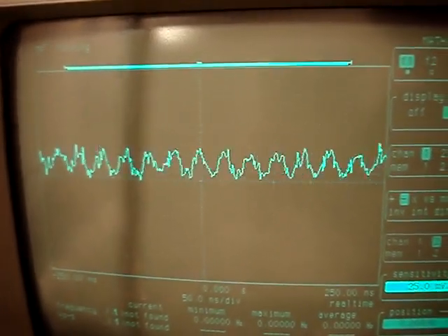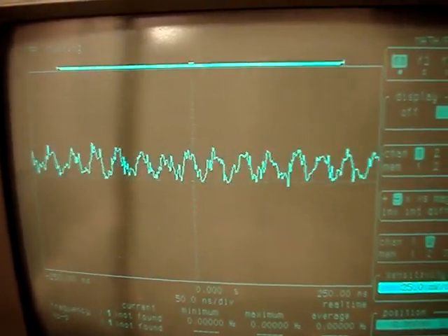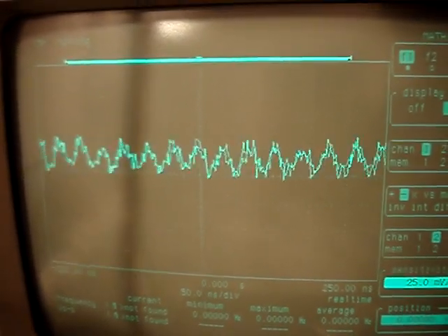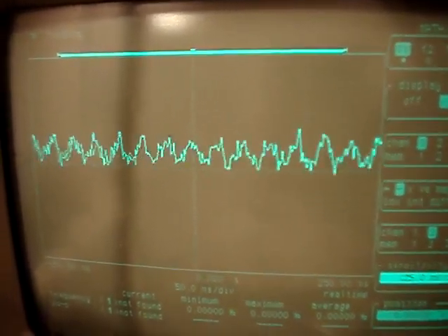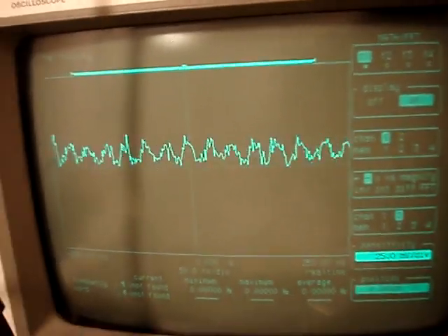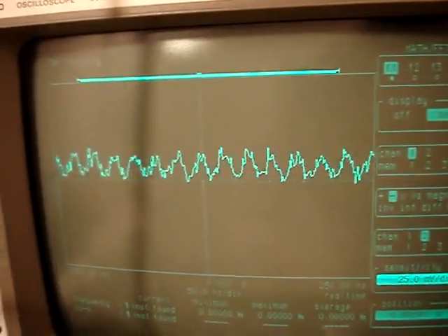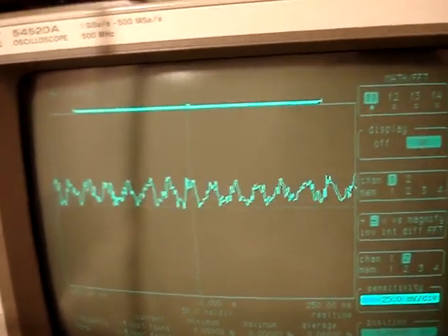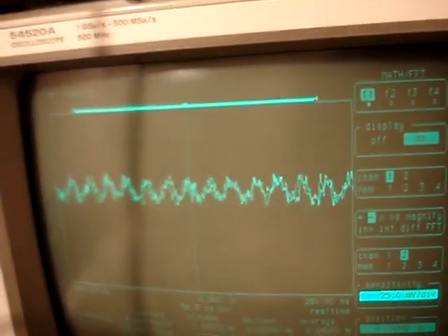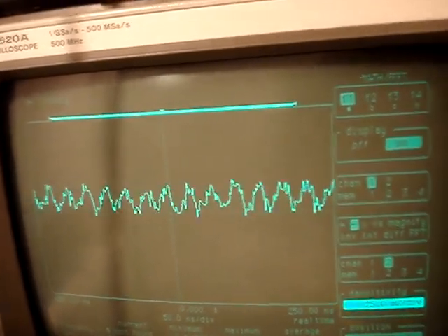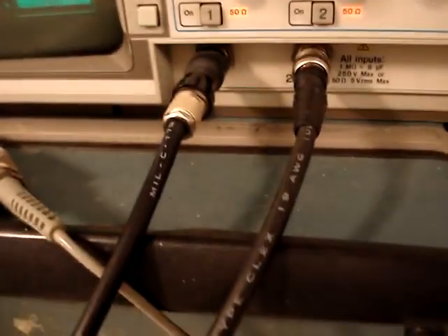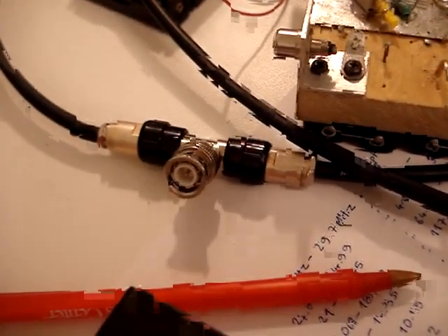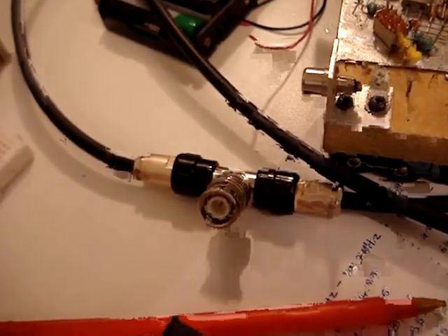this might not actually be the amplitude difference, but tiny variations in the phase difference between the two signals that may have been introduced either by the splitter or by the slightly different cable lengths. I've said at the beginning that I have put two equal lengths of cables, but I actually have different connectors in the cables, and one of these cables is using a small adapter.